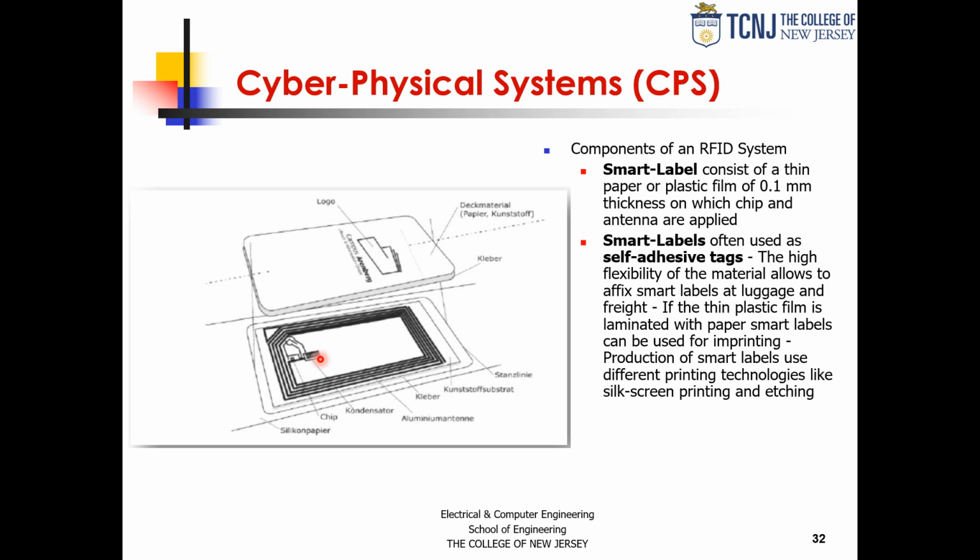And physically, how much charge you can store depends on the physical size of the capacitor. So that is a constraint. You know how much energy you need to do a transaction, and then you can easily calculate how much charge you need to store, and how big the capacitor needs to be. A simple parallel plate capacitor with rectangular plates.